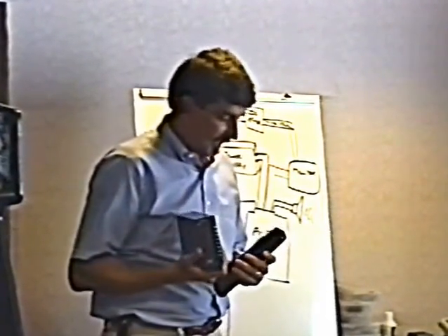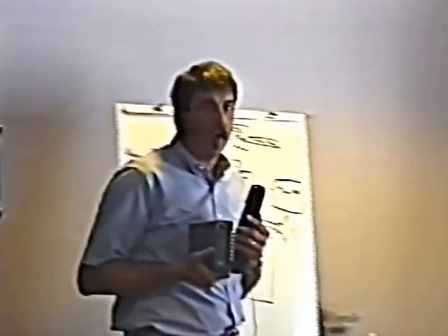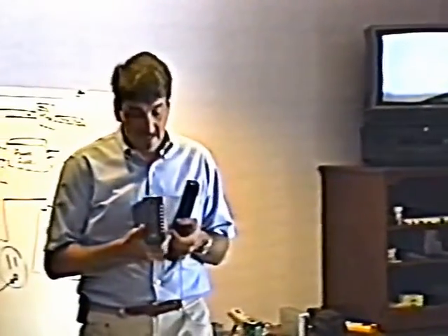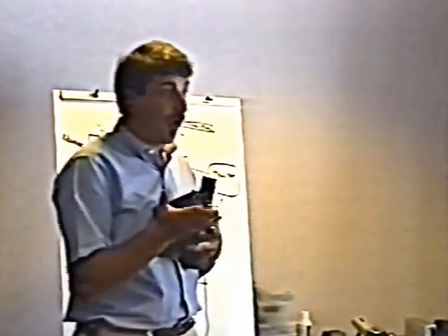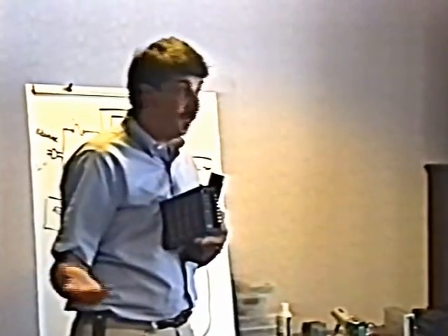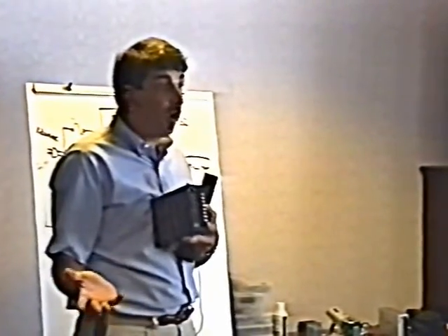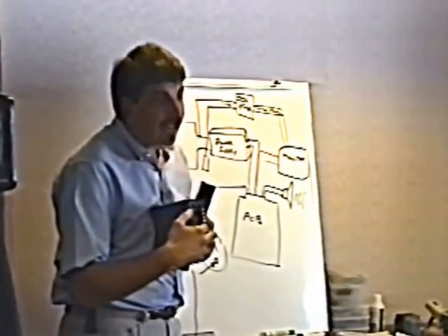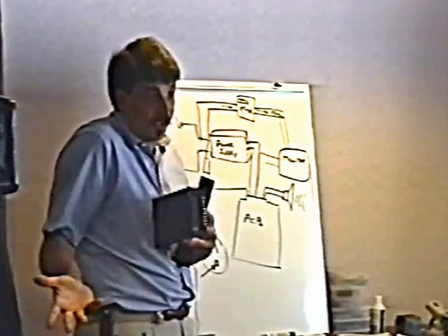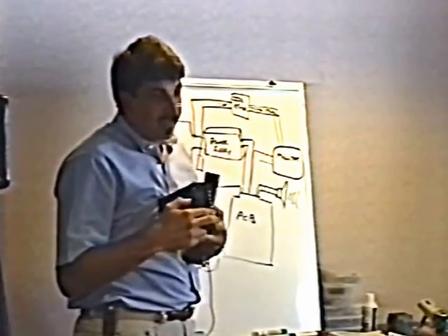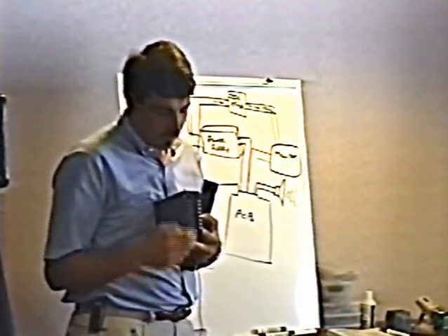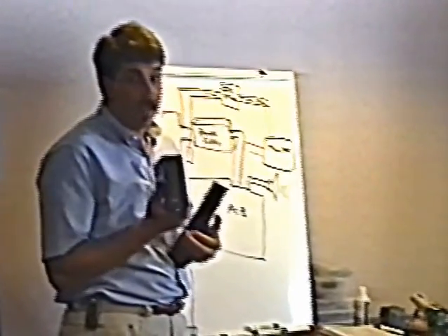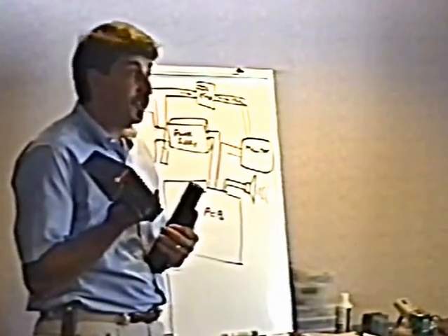Well, we have a saying in electronics, and the saying is garbage in, garbage out. What garbage in, garbage out means is that when you get a bad output from something, check the input. If the input's garbage, obviously the output's going to be garbage too. What I'm saying is, okay, you don't have 5 volts coming out here, check the AC input. Make sure you got your AC in. But if you have your AC input, which you probably will, to be honest with you, and you don't have any DC out, then the power supply is bad, of course, and that's how you determine that the power supply itself is bad. That's pretty simple, huh?